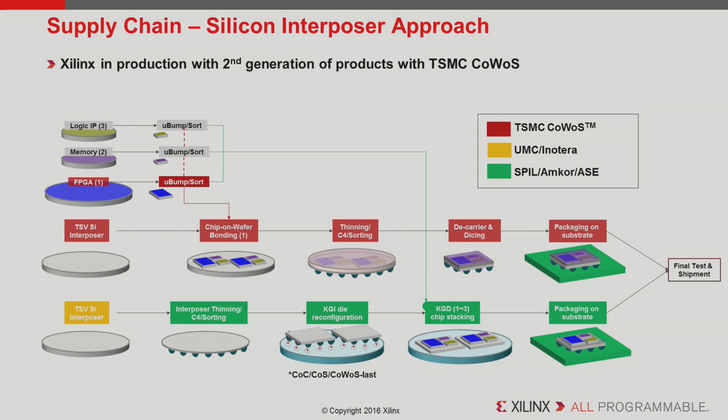And the reason is it lends itself to a very flat configuration from an assembly and yield perspective. That's very important, especially when you have very large SoCs and a lot of microbumps, right? And if you're integrating multiple dies, the yields need to be above 99.99 something, right? So warpage management is actually a very critical factor.